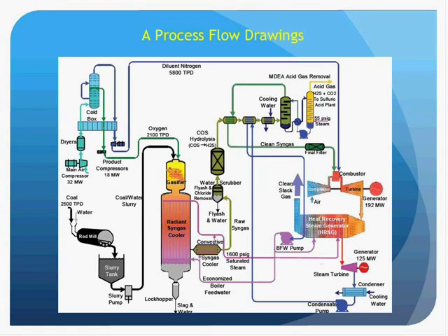The process purifies coal to remove its sulfur content prior to burning. In this process, the coal is converted to a gas. Air used in the combustion process is separated into nitrogen and oxygen. The nitrogen is used to cool the turbine, and the oxygen is mixed with the gasified coal and then burned. The outcome is power production that requires 15% less fuel and achieves 10 to 12% more efficiency than normal generating stations.